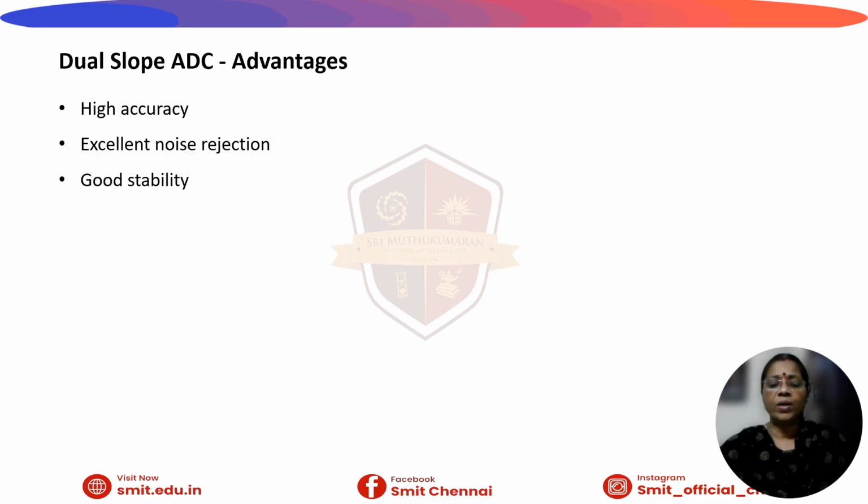The advantage of this dual slope method is that it has excellent noise immunity. The integration naturally cancels out high frequency noise and AC line interference, and it gives high measurement resolution. The disadvantage is that it has lower conversion speed because it relies on two time-based integrating phases.